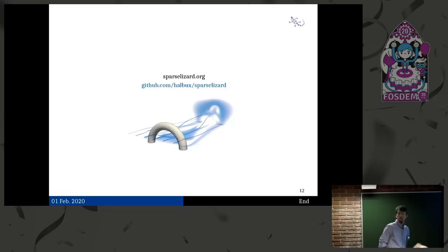It's generated. What I didn't fully understand is whether my stiffness matrix is built explicitly or built up. The way it's built, I call a function that creates a math object which includes all the terms of the stiffness matrix. This is created in basically the core of Sparselizard, a function that calls everything that needs to be called and just assembles very efficiently all the terms in the stiffness equation.